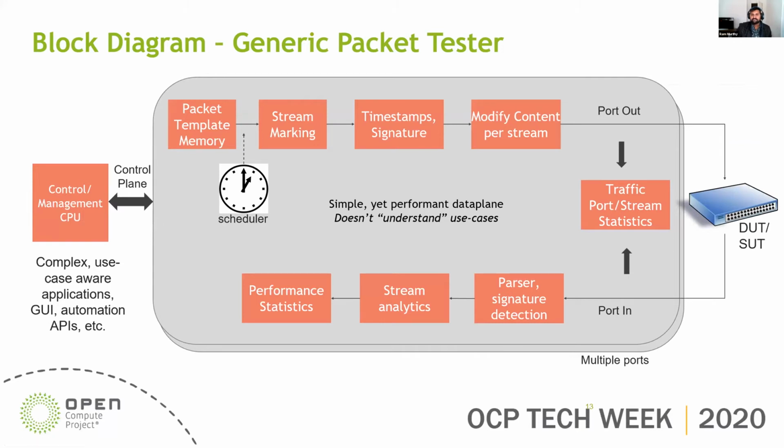So digging a little deeper into the building blocks, we can represent the primitives in a block diagram to really understand what the pipeline is going to be. At the minimum, the tester needs to be able to send specific packets at a target rate and instrument those packets as needed to analyze on the receive side. The receive side will then analyze those incoming packets and collect the metrics associated with the flows based on the instrumentation found in the packet. So both on the Ingress and Egress pipelines, we also need to give you statistics in a way that the software can effectively correlate to really show what's happening in the data plane side.